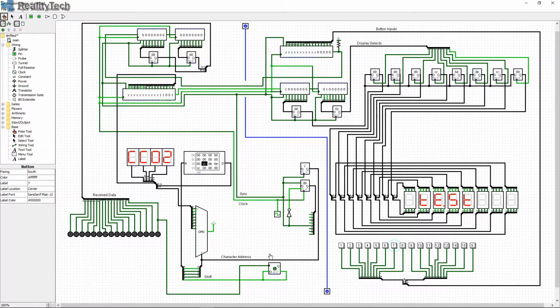So we'll start at the beginning. We'll go full loops. We'll go round this way to the displays and we'll go back. So we've got our same clock here that's generating our synchronization pulse. We've also got another counter here. Now if you see, this one only counts up to 7, and that is a 4-bit counter, which is outputting 4 bits here, which are used to work out where we're going to look in this ROM. We'll come back to that in a second.